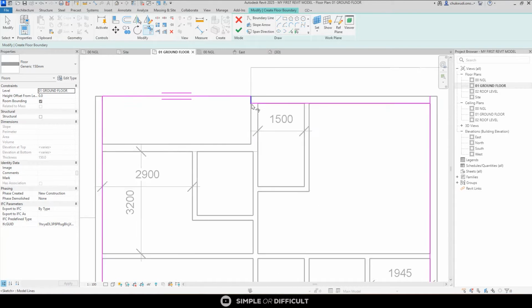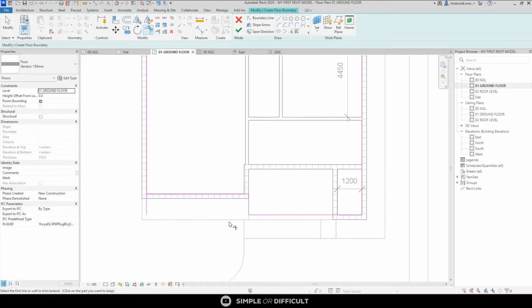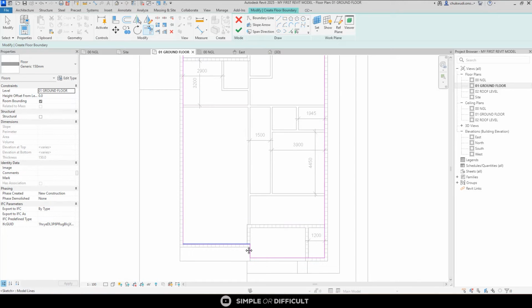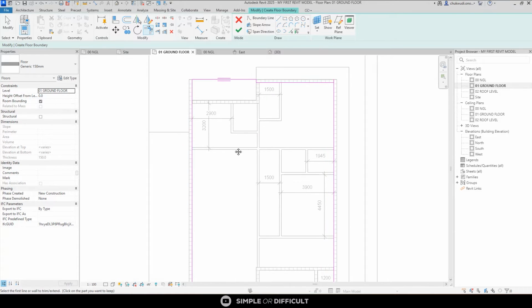I like to create my walls on the inner part of the wall so that you're not going to leave the double line mark of the wall on the surface. Okay, that is the easiest way you can do that. Now, when you are doing your section, you can now use fill region to cover up the part that is not showing as you might want it to show. All right, so that's that for that.